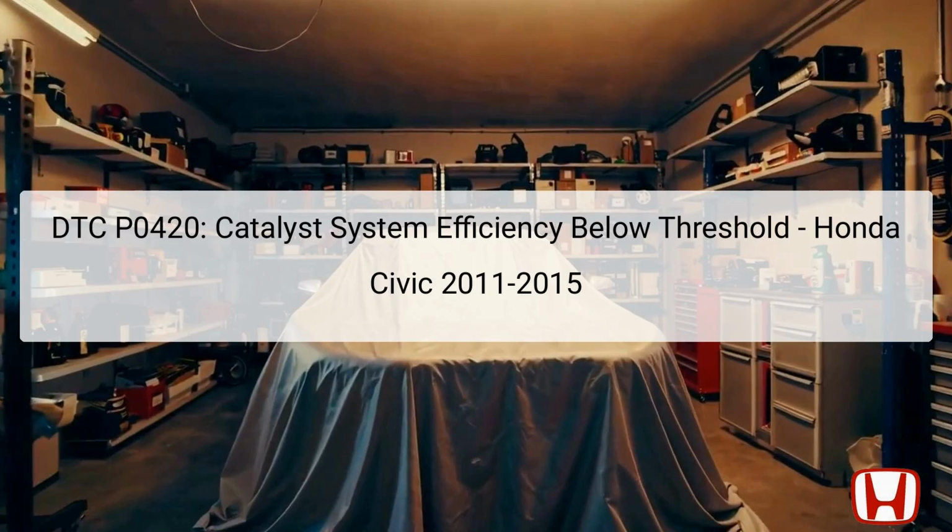The catalytic converter, located in the exhaust system, is responsible for converting harmful gases into less harmful emissions before they exit the vehicle. Oxygen sensors monitor the level of oxygen in the exhaust gases and help the engine control unit manage the air-fuel mixture for efficient combustion. Proper diagnostics are essential not only for regulatory compliance, but also to ensure optimal vehicle performance.